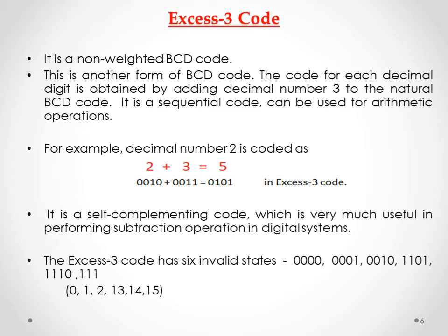Then the Excess-3 code has 6 invalid states. The 6 invalid states are 0, 1, 2, 13, 14 and 15. This code is very useful for performing subtraction.